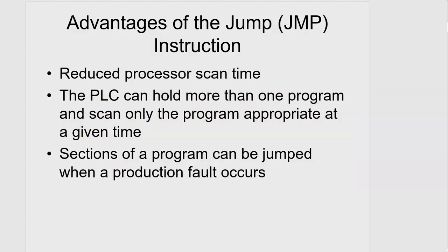So let's talk about some of the advantages of the jump instruction. First, like the other instructions we talked about, it reduces processor scan time, because you're skipping over parts of the program that you don't need at that particular time. If you did not have one of these program control instructions, each rung of the ladder is read or scanned sequentially, whether it's needed or not. So by using a program control instruction like jump, if you know you're not going to use that portion of the program, why scan it? That saves scan time, especially if you have a really long program.